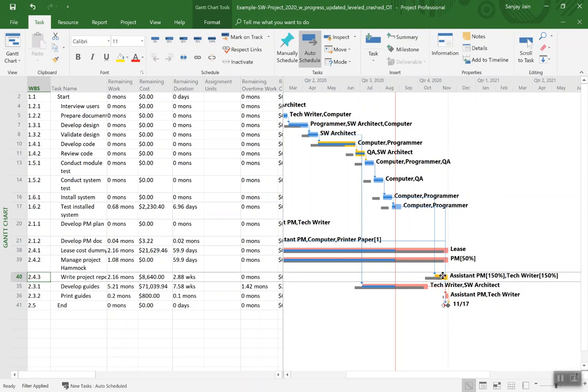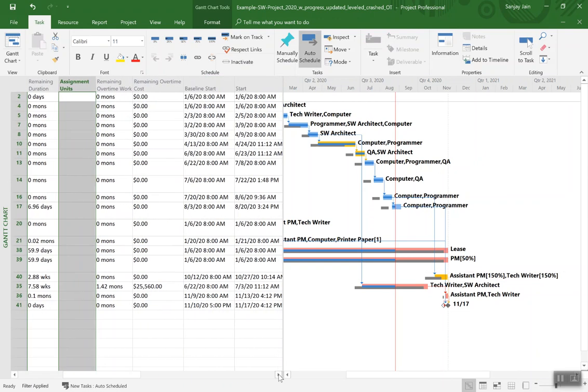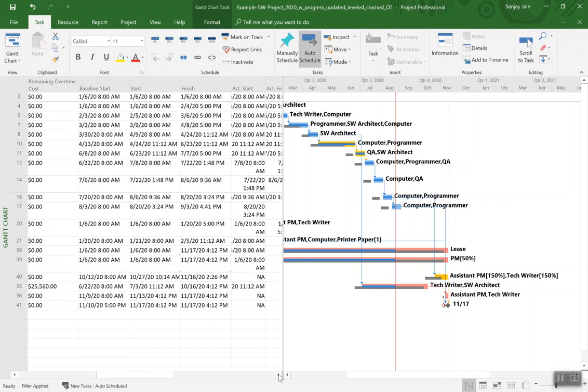So the second activity which we crashed, because that was directly connected to our end line, did pull back the finished milestone some. But since the other activity is linked on a resource critical path and not a directly critical path, we'll have to manually pull back the activity to close the gap here. And so to do that, let's see if we already have the columns. If I scroll to the right, we have baseline, start, and finish. And so we are going to make these corrections.